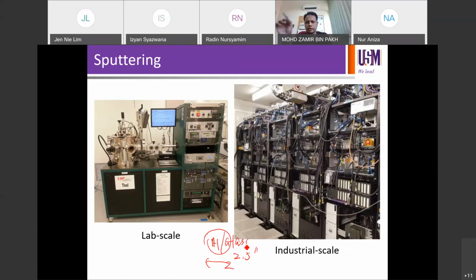It has 20 chambers in series, 2 stacks. One row is on the top area, and another row is on the bottom area. So you have 10 sputter chambers at the bottom, 10 sputter chambers at the top, and below here is all the electronic system, controllers and stuff.